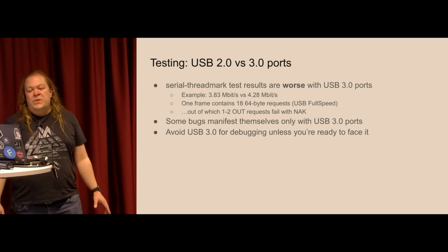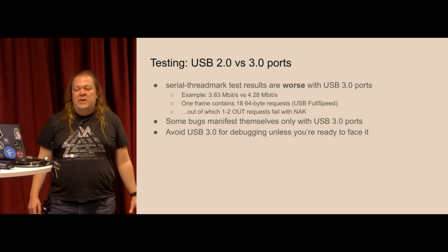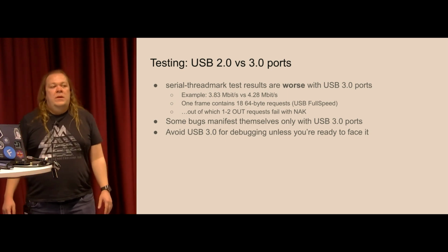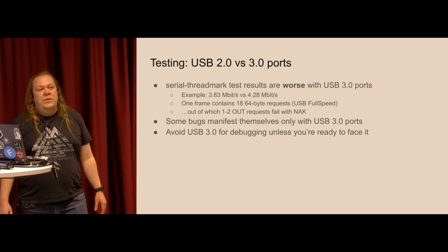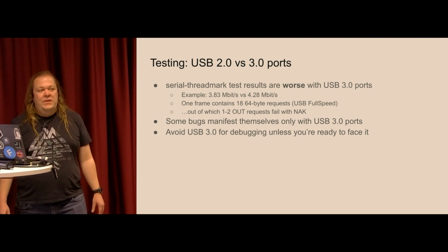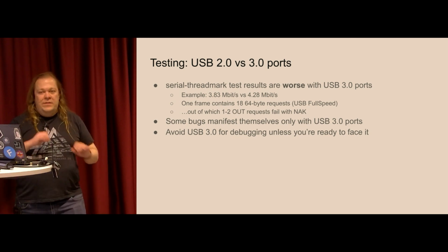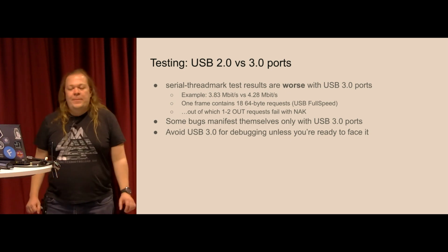Another reason with USB 3.0 is that some bugs manifest only with these ports. For example, the current implementation of USB OTG with high-speed devices just fails the test completely when you plug the device into a 3.0 port. Works fine in 2.0. There are some bugs.